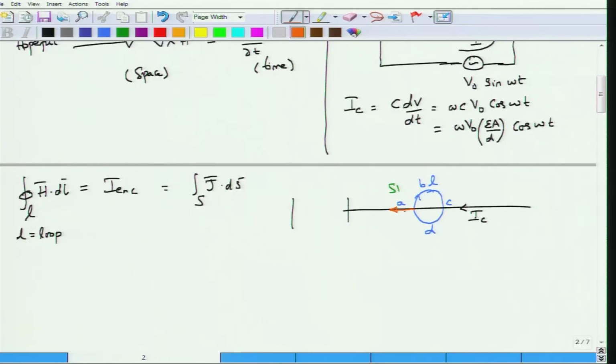If you are not happy with this infinite current density, you can assume that the filament has a short radius r, and take the limit of r going to 0. So the current density can be assumed to be uniform, and if you look at this surface, the current density vectors are all uniform and coming out.